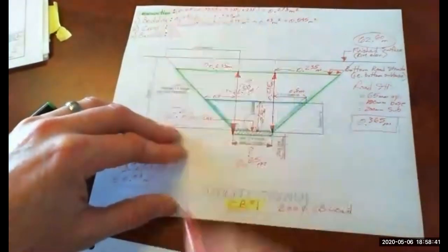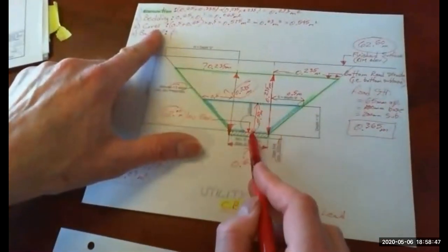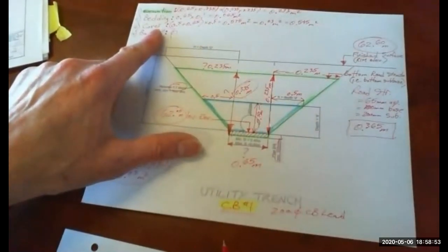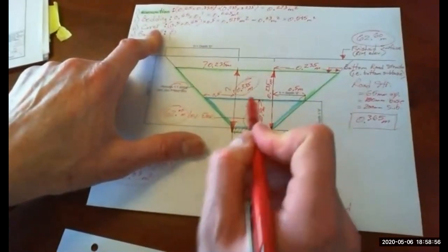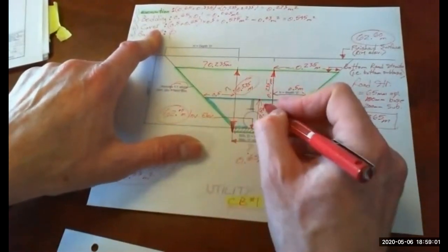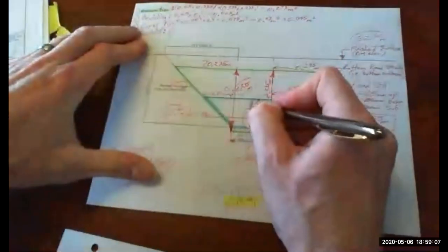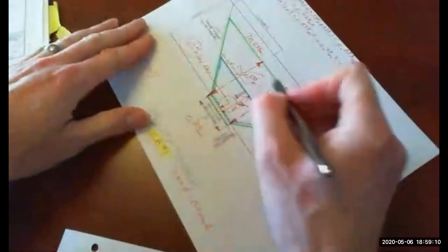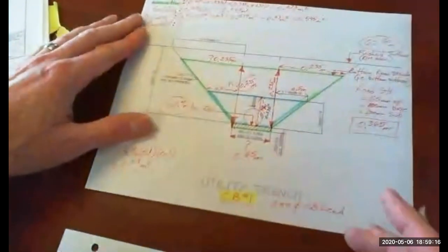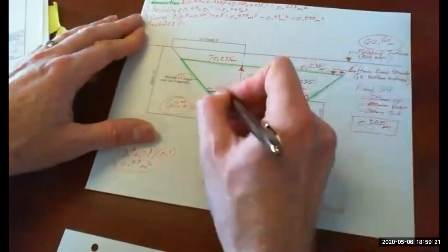So our backfill is going to be 0. And actually our cover is no longer 0.5 deep. It's 0.235 deep, which puts it just barely over the pipe. So let's revise that. If I grab a different pen here. So this here is going to be this number here, so 0.235. Our width doesn't change. This number will change. And this number will change.